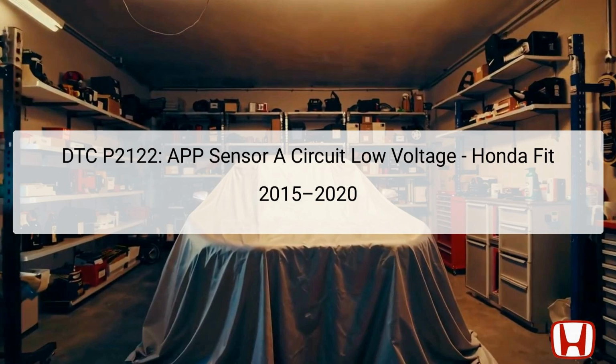The APP sensor plays a critical role in the vehicle's performance by measuring the driver's accelerator input and sending the corresponding voltage signal to the powertrain control module (PCM) in real time. Located at the accelerator pedal assembly, the APP sensor ensures responsive acceleration and optimal engine performance. The Diagnostic Trouble Code is confirmed when the signal from the sensor shows less than 0.2 volts and is observed on the Honda Diagnostic System (HDS) during troubleshooting.